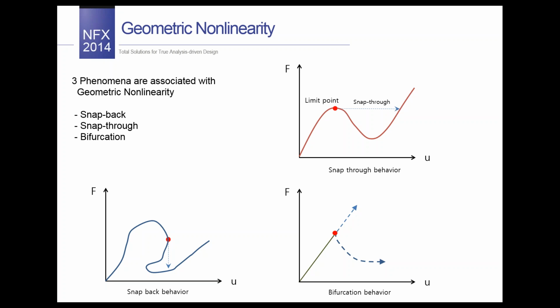Buckling analysis is a special case of geometrical nonlinear analysis that deals with equations classified in mathematics as eigenvalue problems. For the linear problems, usually we receive this value at this point, and we are not able to investigate what's happening after buckling. So it's not possible to analyze post-buckling behaviors.